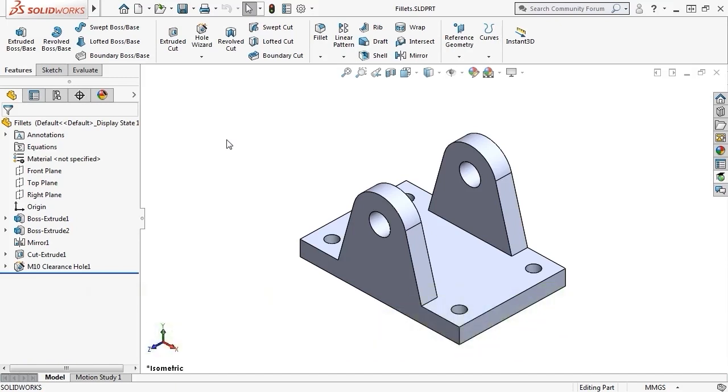To complete this bracket component, we'll be working with the Fillet feature to break all the sharp edges on this model. Before I begin, I would like to quickly mention a few rules of thumb that are good to keep in mind when it comes to fillets. Generally speaking, it's a good idea to save adding cosmetic fillets until the end of the part. Second, I recommend creating larger fillets first, and then creating smaller fillets after. As your models become more complex, you may have areas where one fillet feature may overlap with another filleted area. When this is the case, there can sometimes be geometry conflicts that exist, but by creating the larger fillets first, this will sometimes help you avoid those geometry conflicts. Finally, I recommend grouping fillets together in the same feature if they are to be the same size.